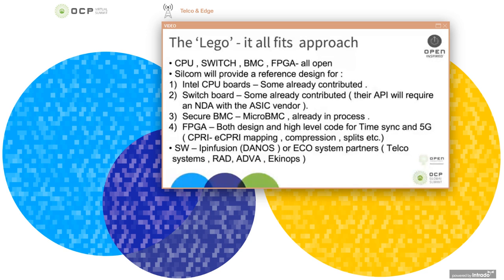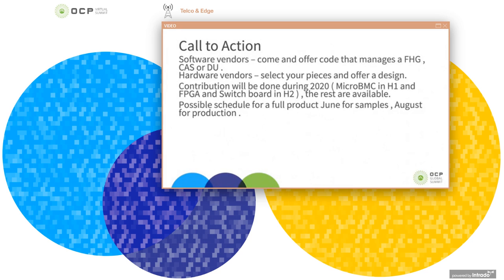Now, the FPGAs are a tricky part because FPGAs are fully programmable, as you know. So on that front, we offer both the actual hardware design of the board as well as a high-level code, meaning like a shell for time sync, for 5G, CPU-to-CPU mapping, compression, splits, etc. And we do this for both big FPGA vendors. So we're hoping that by giving you both the hardware design, reference designs and tools, and the software code, more clients and more users will be able to take that and build some of their own.